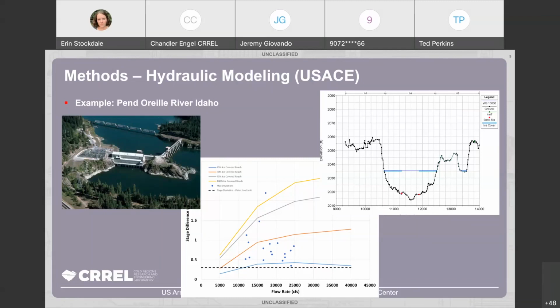And then this allowed us to figure out a probability of that occurring based on the probability of ice thickness and also the probability of the certain flow rates that we had. And so now Seattle District, who operates this, they actually have a way to figure out the probability that the units may be turned off given certain river ice conditions.